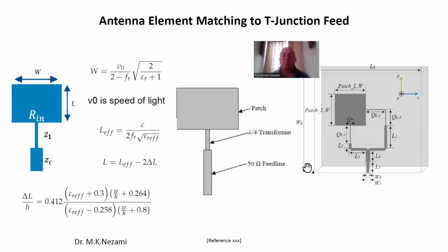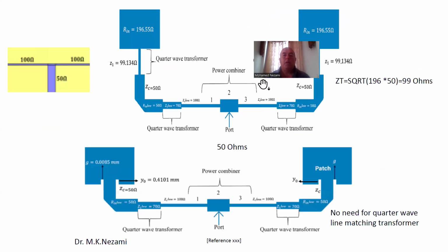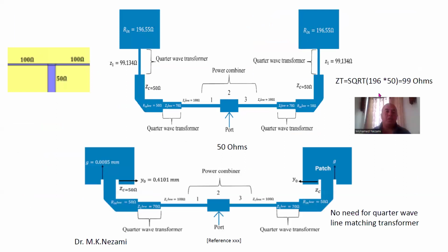Okay, so this principle. Now, like we talked about, look at this, how neat this is. So assuming that you have two elements of this type and this type, we have a 50 ohm input, and we have 200 ohm lines in parallel. Then we have to get from this 100 ohm to this 200 ohm with a 90-degree transition.